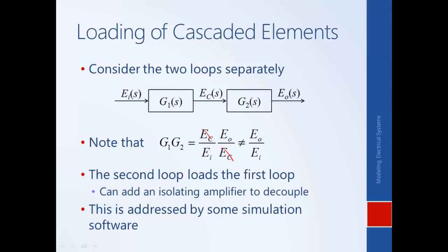In particular, simulation software that is called physical modeling tools, that actually are aware of what's being modeled, for example circuit simulators like PSpice or SimPower Systems, that actually know that what's being modeled is a circuit, will take into account this loading effect.